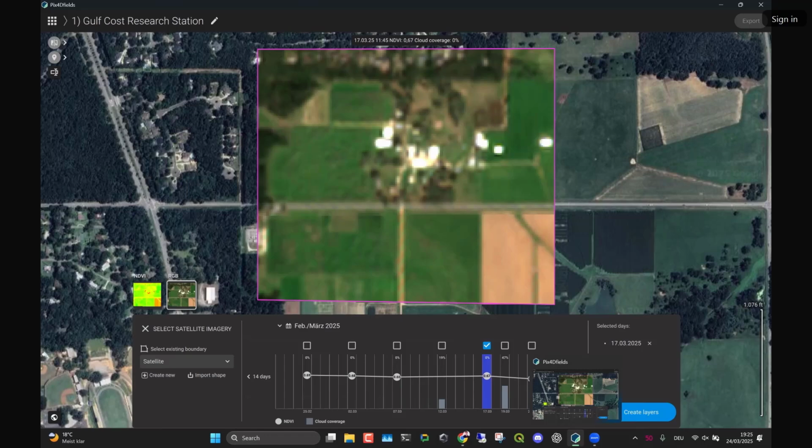Type NVIDIA in your start menu, go to the 3D settings, and make sure the program Pix4D fields is set to high performance. If you don't, you're probably losing 30% in processing speed, maybe even more. On a Mac, you don't have to. It'll run on a Mac desktop very well.